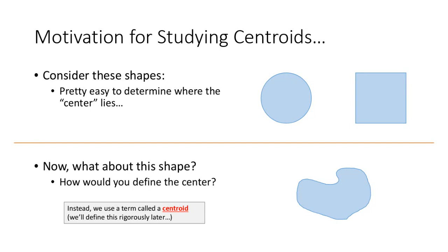They're values, scalar numbers that represent a region in space. Just like the square. I've got a square here, so what characterizes its cross section? And when I say cross section, sometimes you'll hear me use the term section properties. Section properties refers to if I have a member and I cut through it and I look at the shape, whether it's a circle or a square or an I-beam or whatever, I'm looking at that cross section. So if I use the term section properties, that's what I mean.